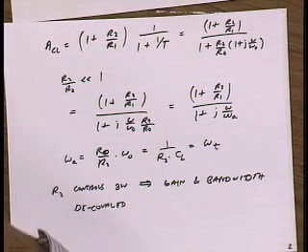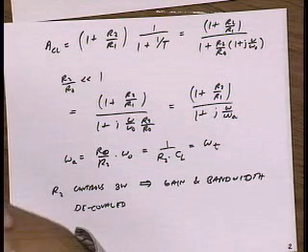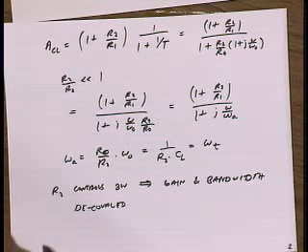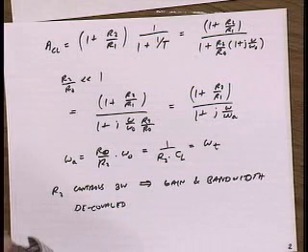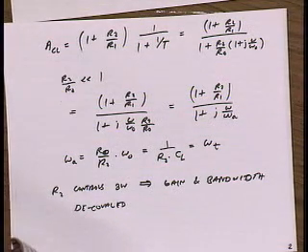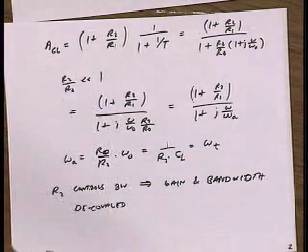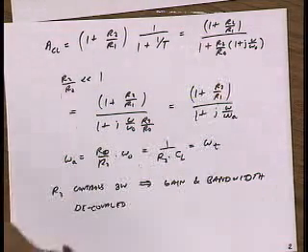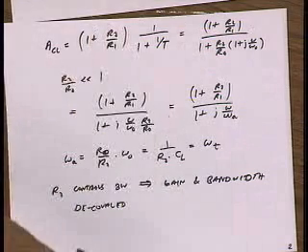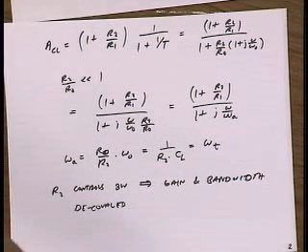I'll give you one hint. Imagine you're a customer and you're buying this amplifier from somebody who's fabricated it for you, right? Why would you be happy if gain and bandwidth are decoupled? It's just nice, right? You select R2, that selects the bandwidth, and then you're always going to get this bandwidth out of the amplifier no matter what feedback factor you use.